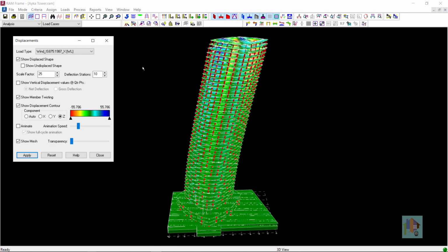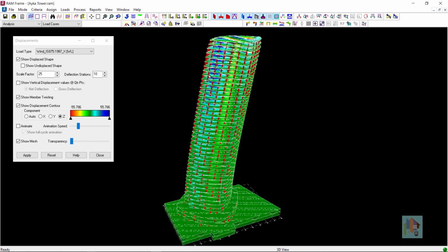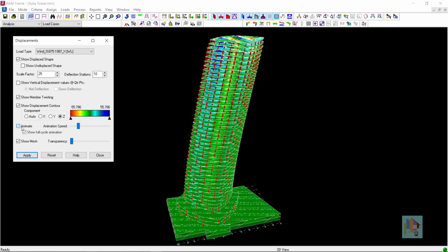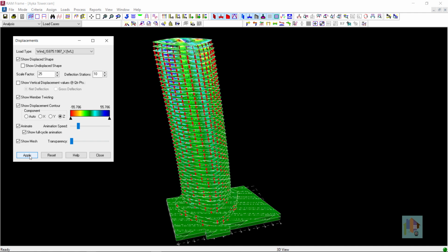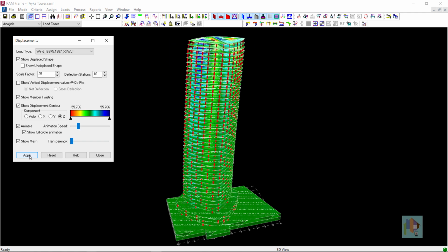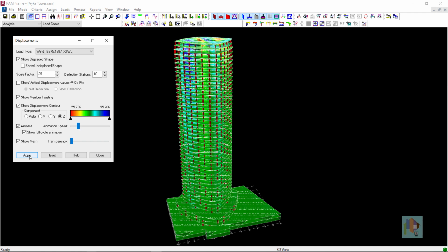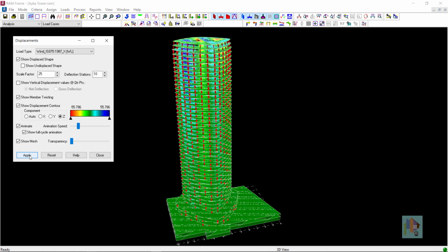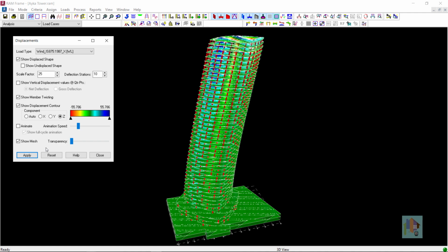There is another aspect which needs to be considered for any tall structure, which is drift. If you consider any tall building, drift due to lateral load at top floors is quite high, and the whole structure moves back and forth due to wind or seismic load. Sometimes the drift is as high as 3 to 4 feet at top level floors. This drift can cause several problems and hence needs to be considered during the analysis stage.